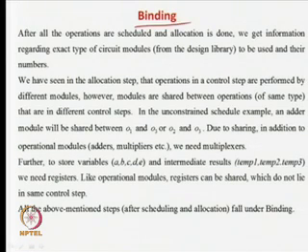So, actually the binding problem is that one. It says which hardware elements bind to which of the operations. Here it says that in the unconstrained time schedule, first example O1 and O3, O2 and O3. There are two hardwares available. In one we do O1, the other we do O2, and then in the second time step we do O3. You can say on adder 1 I do O1, or on adder 2 I do O2 and O3. So, O3 can be bound to either A1 or A2, the two adders.